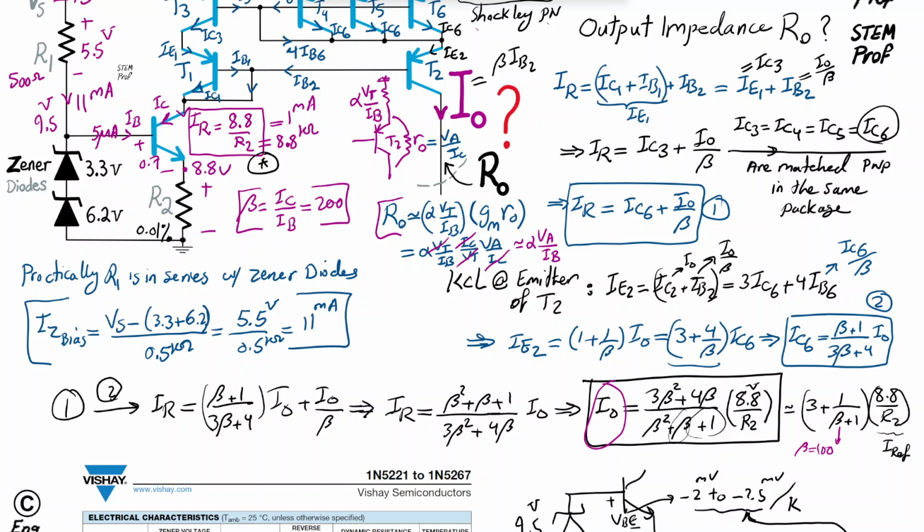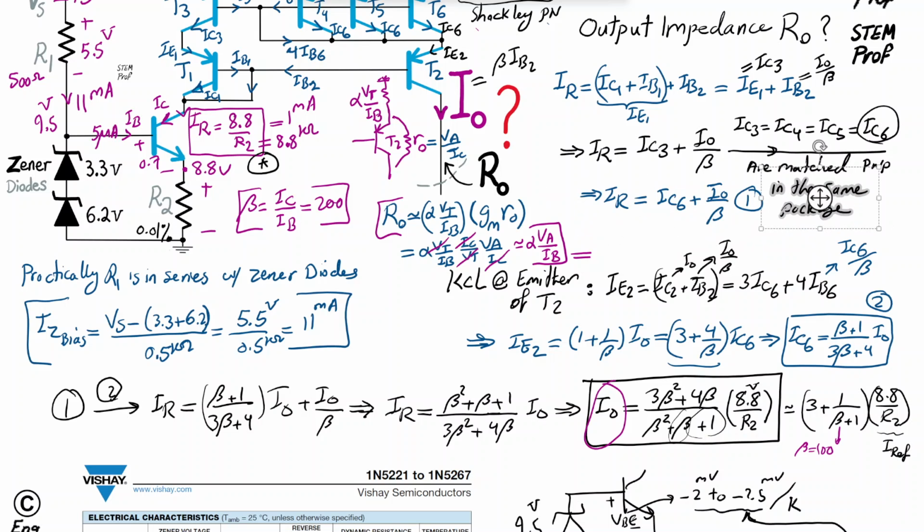Now, the beauty of this is usually the early voltage. Let me move this to a better place so that I have some more space for this last conversation. This is enough for me. Okay, so I'm going to move this as well here. Perfect. So what's happening is this early voltage is usually on the order of 200 to 250 volts for nominal BJT transistors. So we are dealing with alpha times 250 or 200 volts, let's say, divided by the base current.